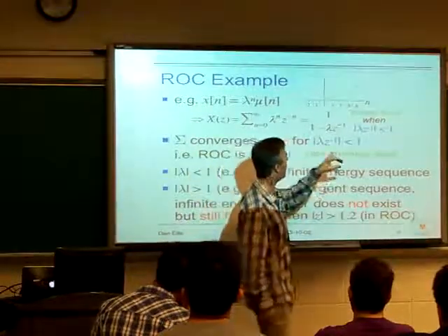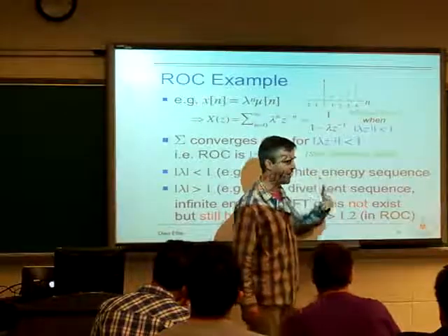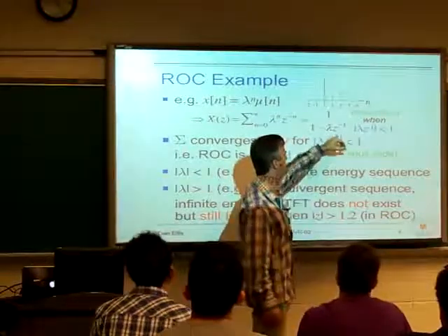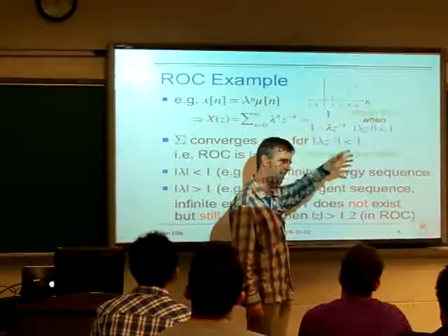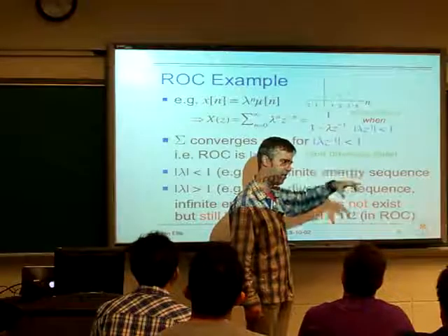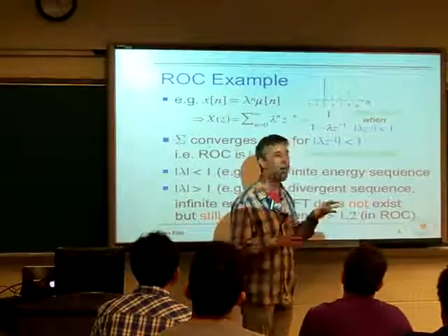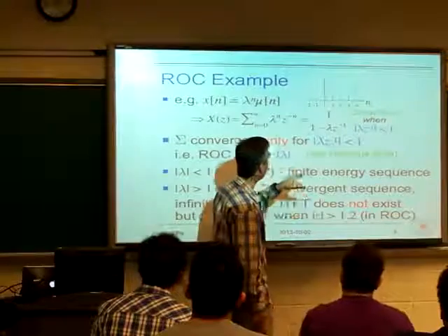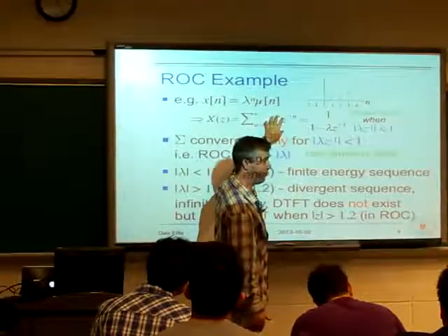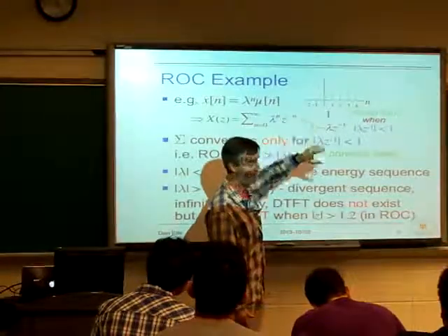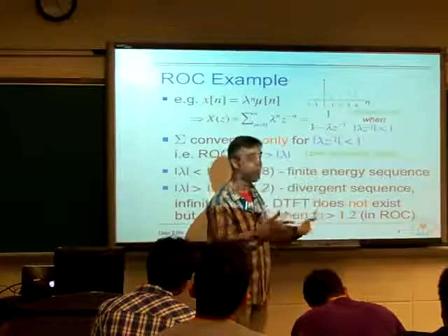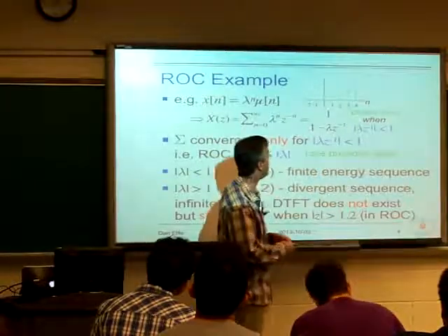And so, the way I was taught this, or the way that I absorbed it when I was taught it, was this is the Z transform, and then there's this thing called region of convergence, which you have to sort of drag along with it, which is somehow part of it. But no, this is the Z transform, which includes these values which are unbounded, which are ill-defined.